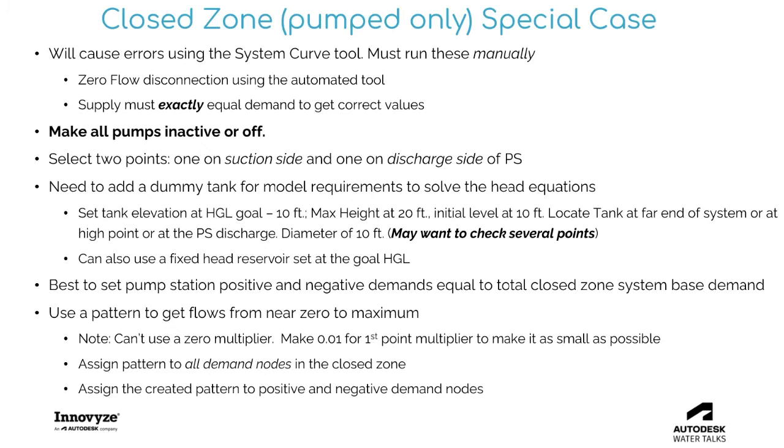So you've got a model zone where you have no tank. It is just a pumped only zone, so a pumped supply only. In those kinds of situations, you cannot use the system curve analysis tool directly.